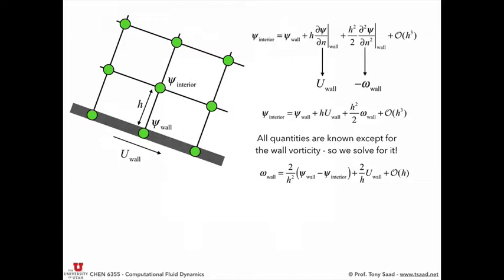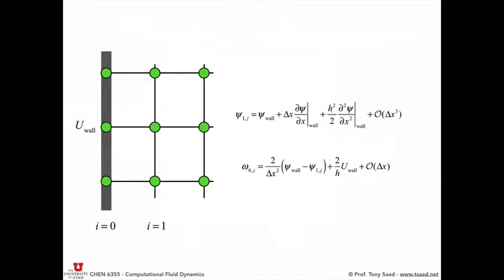If you want to add one more term, what do you do with the third derivative for the stream function? Okay? So we're going to take this formula and just apply it to the left wall. This sign remains the same. So this is the general form. In the code, we're going to set this guy to 0.